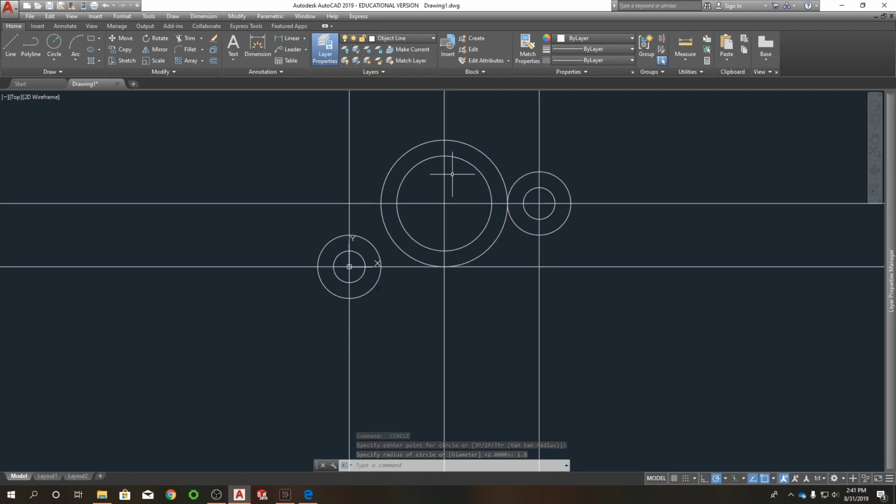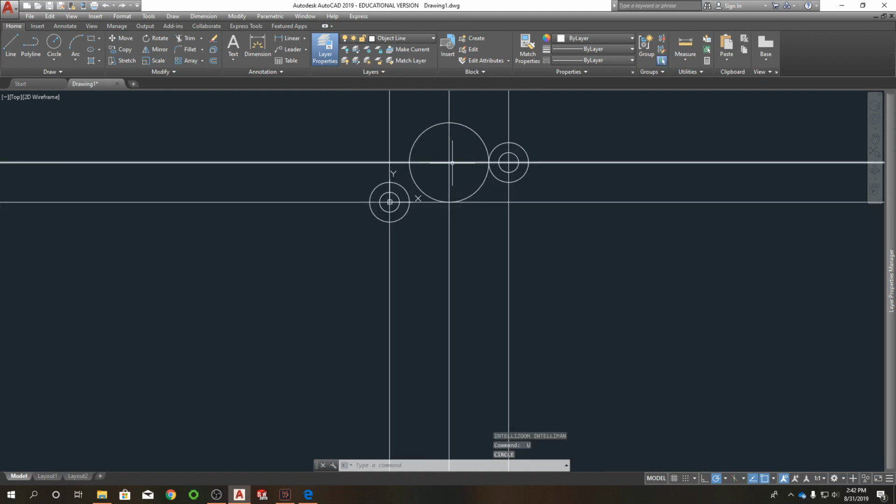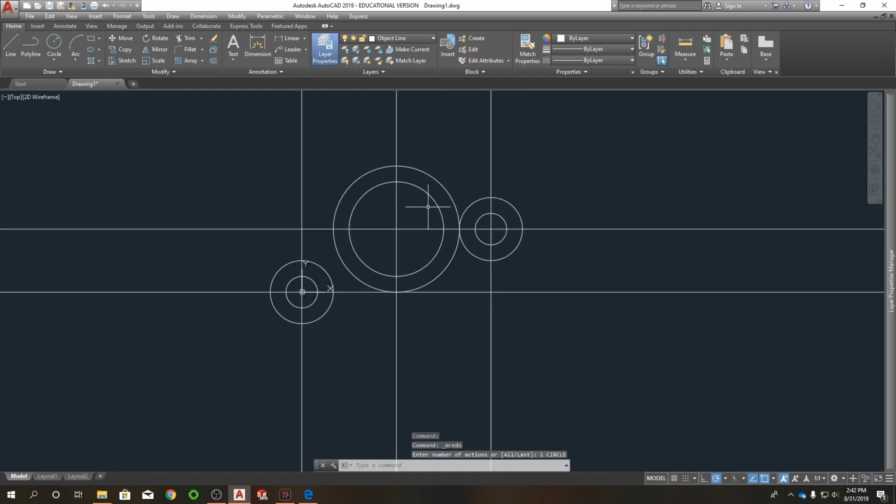And then I'm going to create a polygon, 6 sides, center right there, circumscribed about a circle because I know that from 2 parallel lines it's 2 inches. As you can see there, I'm going to set it to 2. Oops, what the heck happened there? Oh, half of 2. Oops, I was on the undo command. Let's try that one more time.